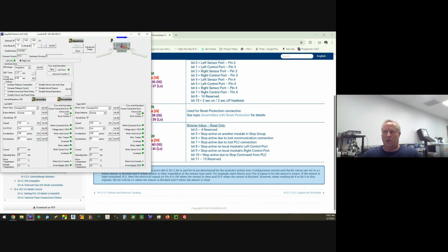Let's say this is the card releasing to that taping equipment. In Easy Roll, you set accumulate. If you power cycle the card, this is saved to the flash memory. So the card will power up and accumulate. Perfect. That was step 1. So the last card powers up and accumulates, but does not release.